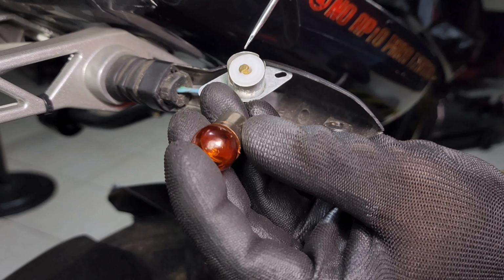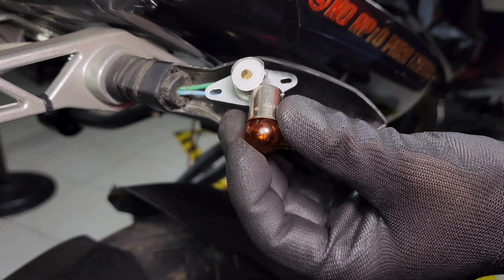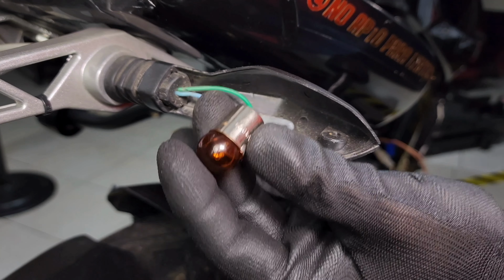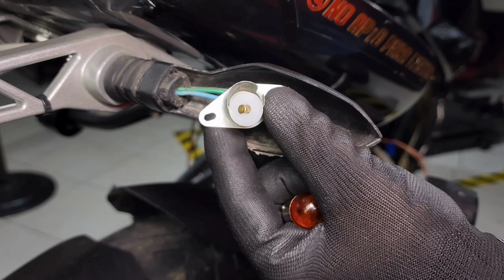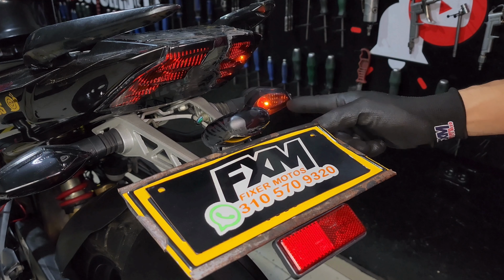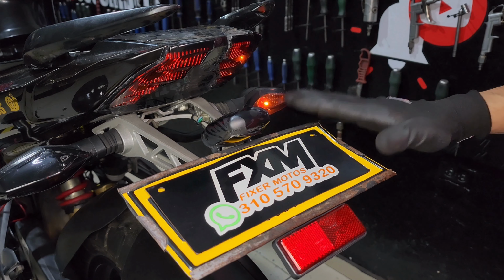But it happens that this part is sulfated, and see, it is physical wear. The physical wear affects the electrical operation quite a lot. So you have to always check these physical parts. So the hyperflashing that we had was due to a sulfation issue. It wasn't a voltage issue, which is what normally occurs.